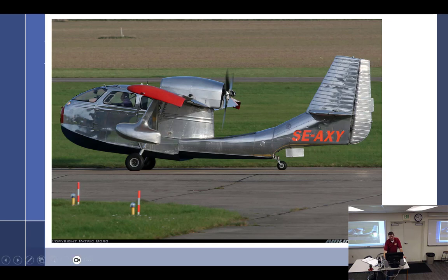Now the thing about the pusher type is, you guys built a Lycoming engine. Does that look like it was set up to be a pusher type? Because your thrust bearing on the crankshaft as a tractor was a very thick piece of metal. And then if it's a pusher type, it's going to be a very thin little slinger ring in there that it's riding against. So consider that. So would the face be